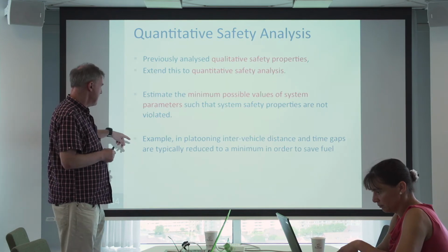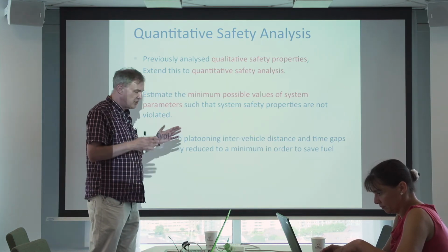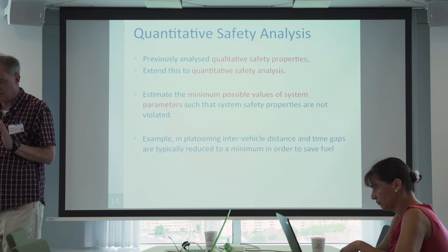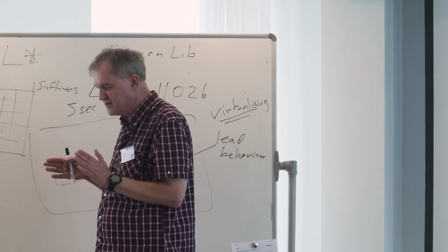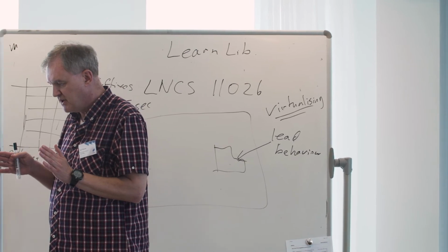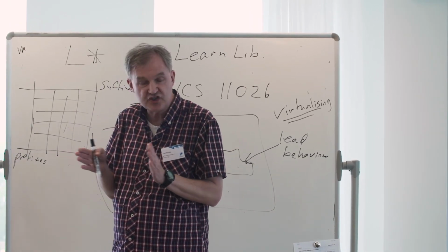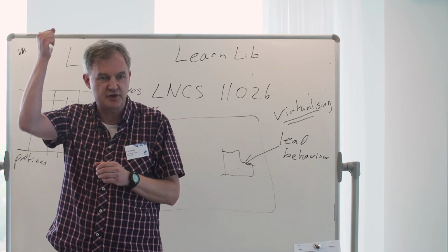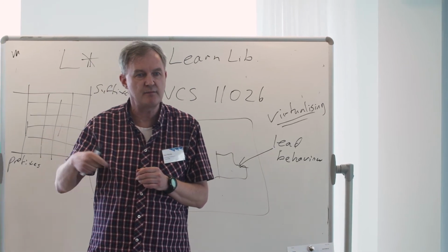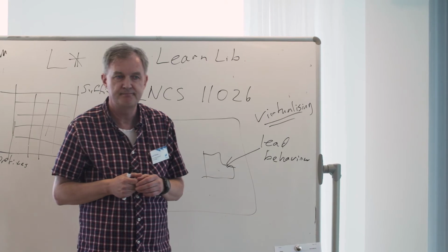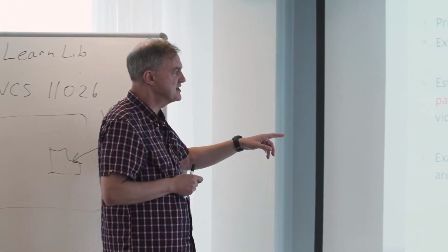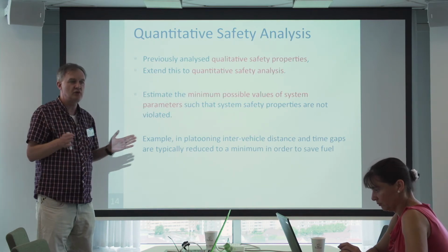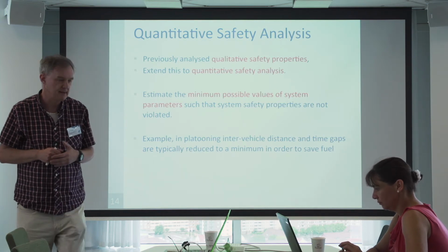So for example, we can look at the time headway between vehicles, and we know that if you respect this time headway, you'll always be safe, according to our massive simulations. But if you bring in e-brake, you'd like to actually allow yourself to bring the vehicles even closer, okay? Because at the very unusual times when chaos breaks out, an algorithm manages the chaos, which it was not doing before, okay? So that could be one hypothesis, that you buy this e-brake algorithm and you can save fuel, because you can run the trucks together more closely, okay?